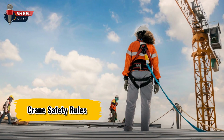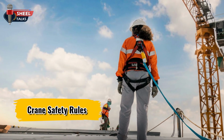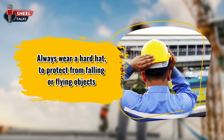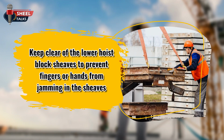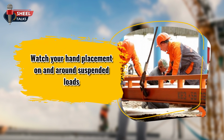Let's consider some important safety rules that should be followed at the workplace. Stay off and away from cranes unless you are assigned to be on the crane. Always wear a hard hat to protect from falling or flying objects. Keep clear of the lower hoist block sheaves to prevent fingers or hands from jamming in the sheaves. Watch your hand placement on and around suspended loads.